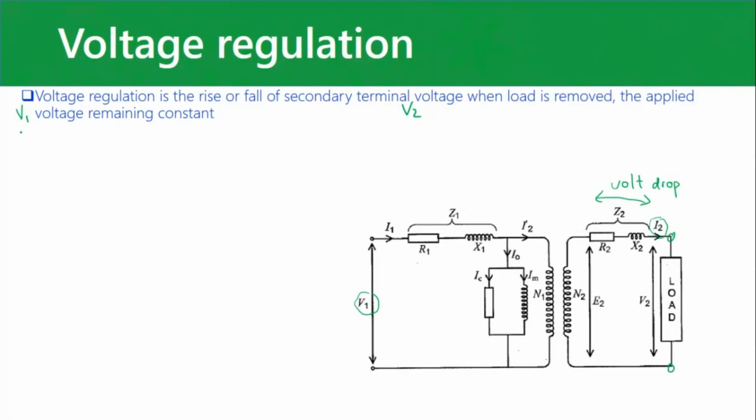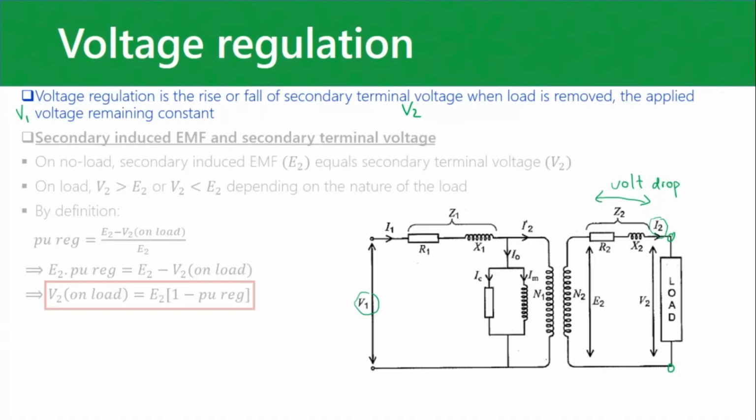So you take the voltage on load, then you open the breaker on the load and cut the current through the load, and you leave the voltmeter on V2. Then you'll measure E2 instead of whatever it was when it was on load. And that is the definition of voltage regulation.